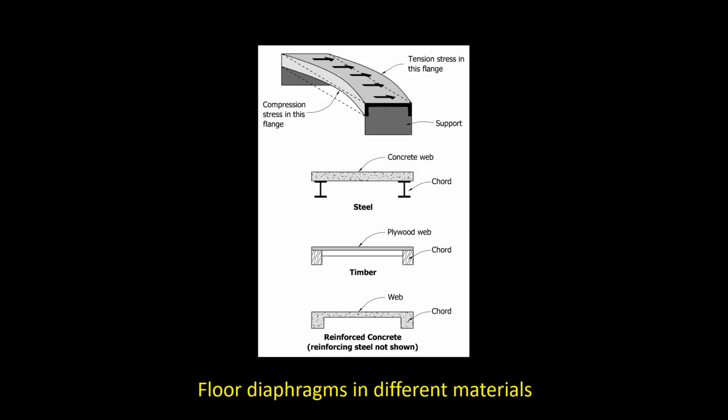And so this is what a diaphragm looks like in a real building. There's the floor slab. Here is a beam, a perimeter beam, another perimeter beam. And so under earthquake, the diaphragm bends, transferring the forces to this support, this shear wall, and that shear wall. Or maybe this is a moment frame into this moment frame and that moment frame.